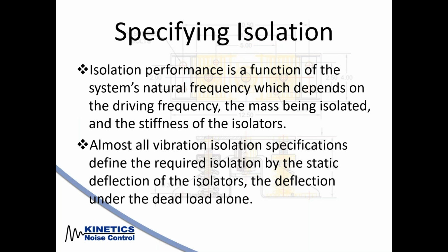So what that means is you are actually looking at, once the weight of the equipment is on the isolator itself, how much deflection are we going to have from the isolator? So it's not an isolator standing by itself. How much squish is going to be applied to the isolator once the weight of the equipment is on the isolators? And a lot of people look at vibration isolation like it's black magic. How do you determine it? And there is actual science behind it when we look at things like the natural frequency and the driving frequency.